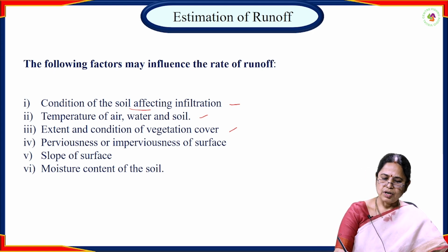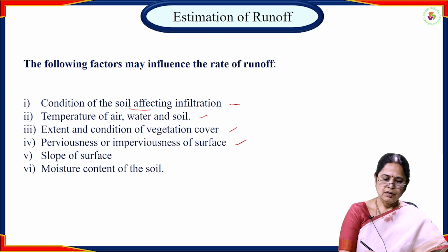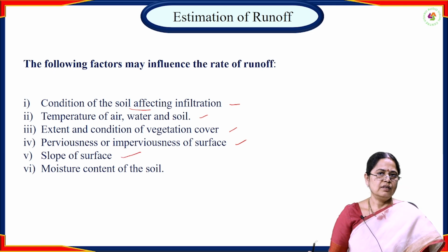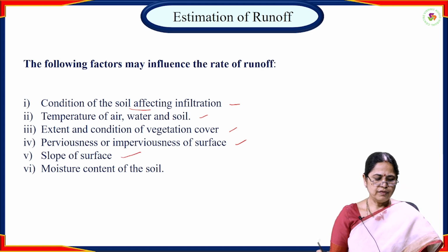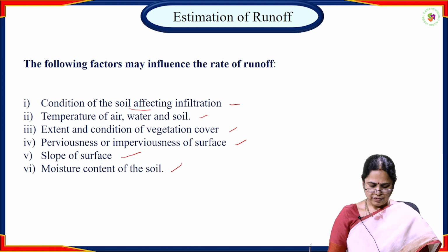The pervious or impervious surface: as the impervious surface increases, the runoff also increases. Slope of the surface generally increases the runoff. Moisture content of the soil also increases the runoff.